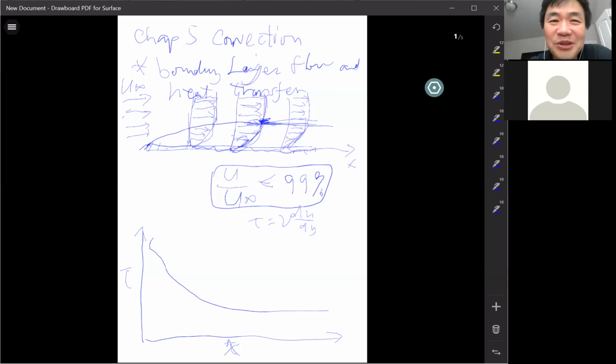So usually it's a trade-off between the heat transfer and the shear. Heat transfer increases. Usually, for example, you put a fin on it. You put something on the surface. Heat transfer increases, but that's the cost. You're going to spend more money because that thing will cause more shear, more resistance, and give you more pressure drop along the flow. Eventually you're going to pay for the pump, and you need to pay for the power, electricity, everything.